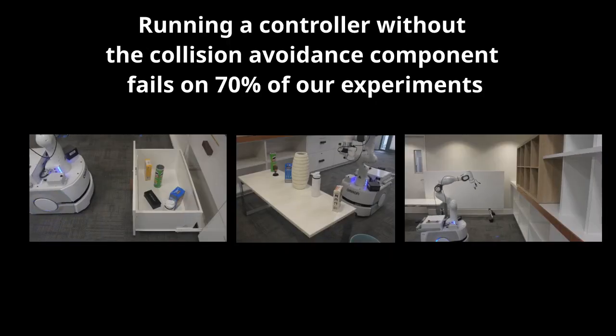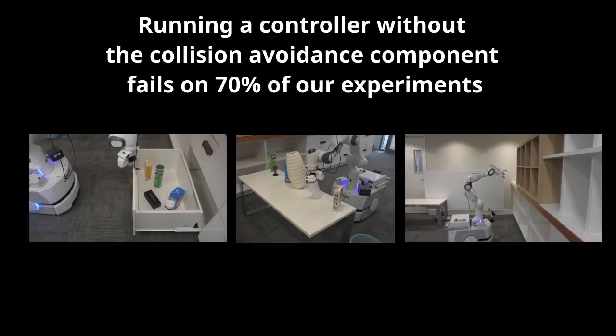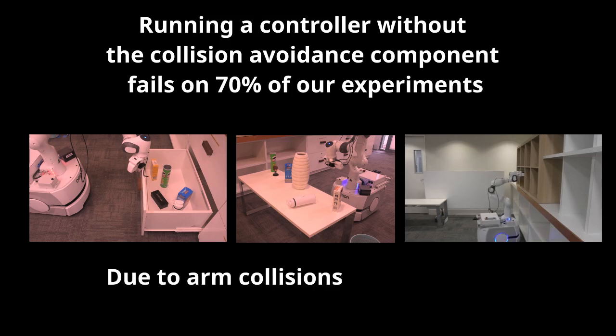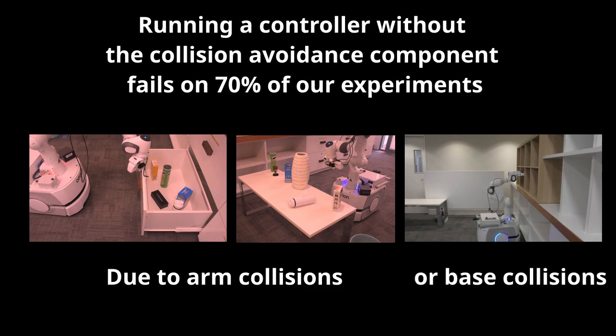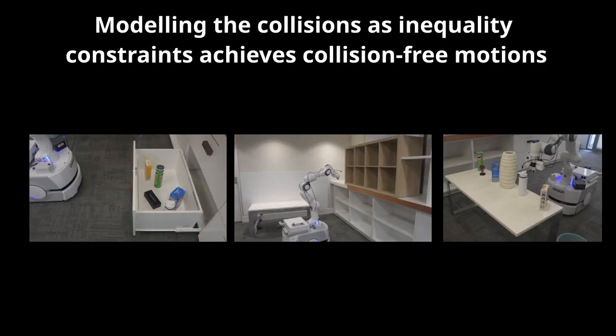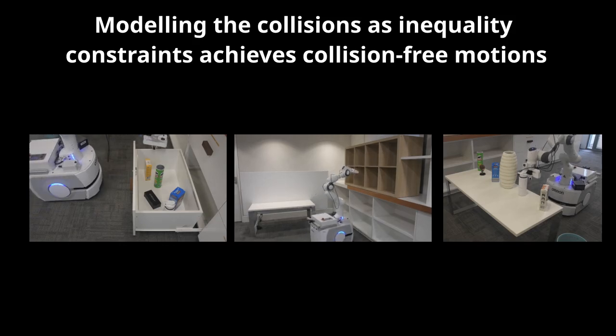Our first result shows that running the controller without any collision avoidance component fails in 70% of our experiments. This is due to collisions on the arm or on the robot base. In contrast, by modeling the collision as inequality constraints, we achieve collision-free motions.